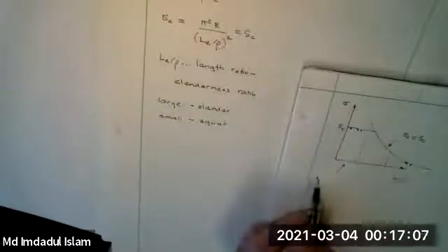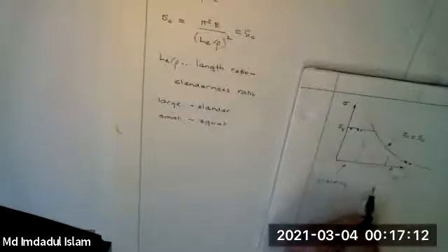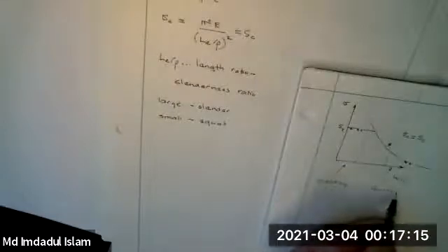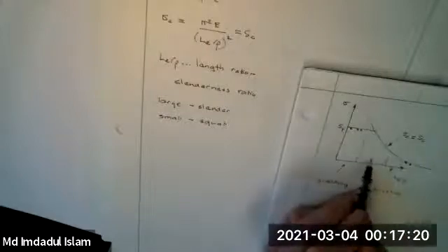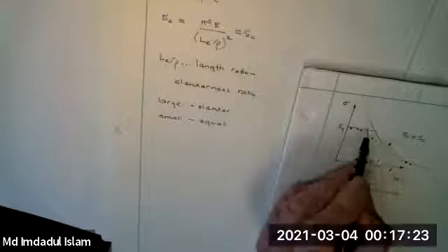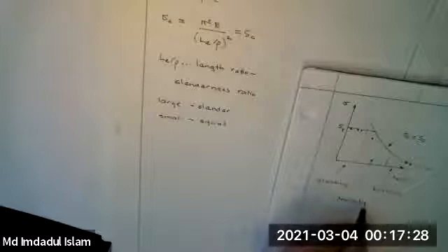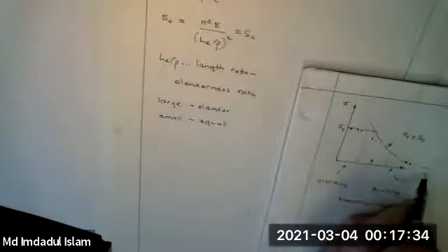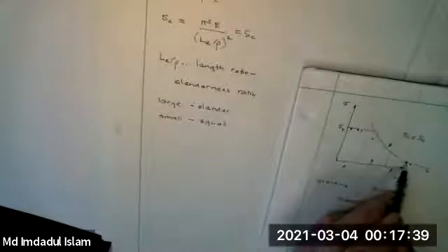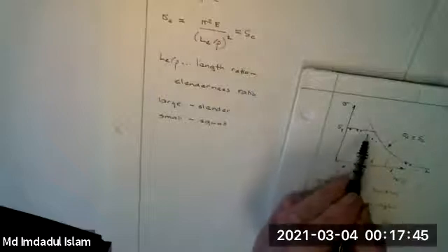So in here we have yielding. Here we have buckling. Here we might have a bit of yielding, a bit of buckling. This is a transition region, and the data doesn't follow this line or this line. I showed you with the ruler that some of this data out here is really low. It tends to be a little bit low, and there are some adjustments for that. I can show you some of those, and you need to have a transition region.